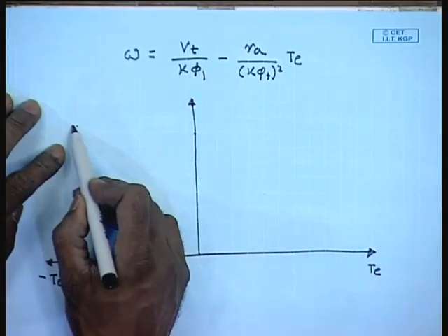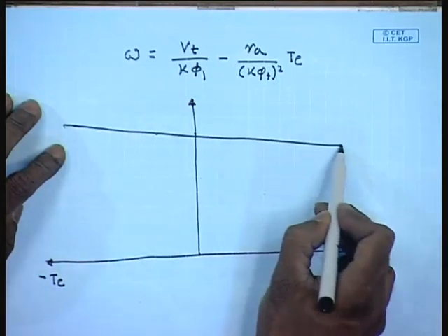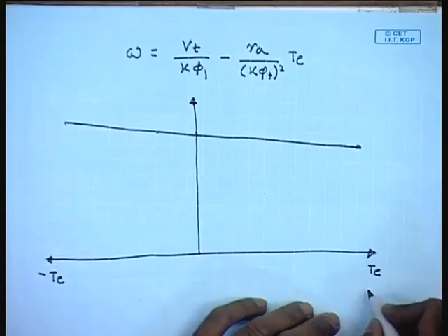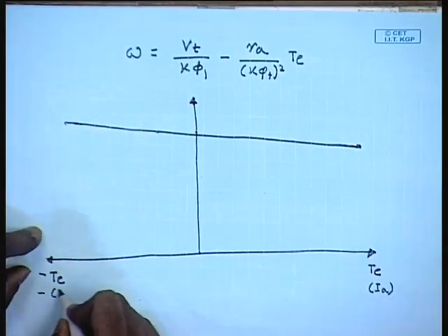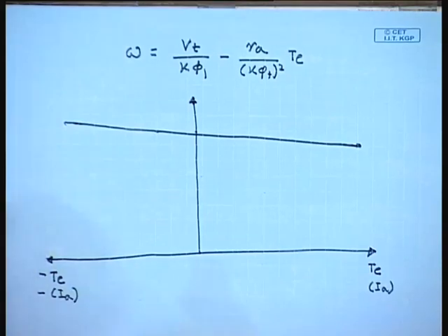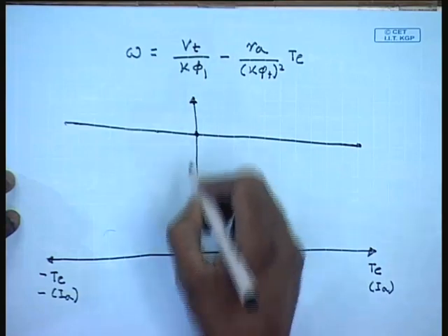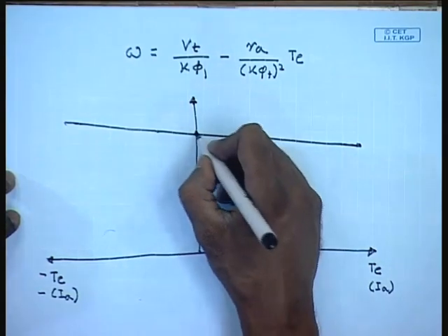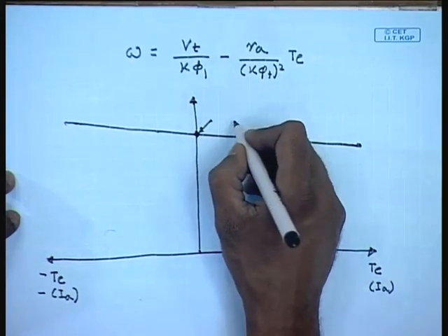since in a DC machine with constant field flux, torque is proportional to armature current. So, this x axis also to a scale represents the armature current. This is the speed at which torque is 0, indicating the machine is operating at no load if we neglect mechanical losses.